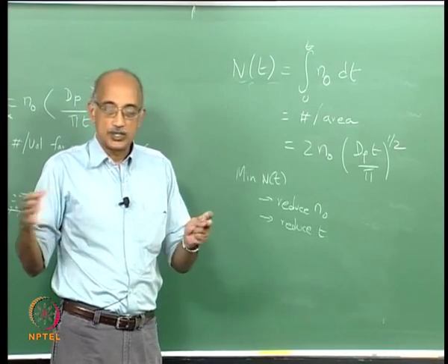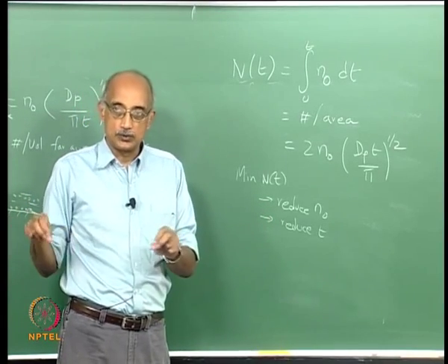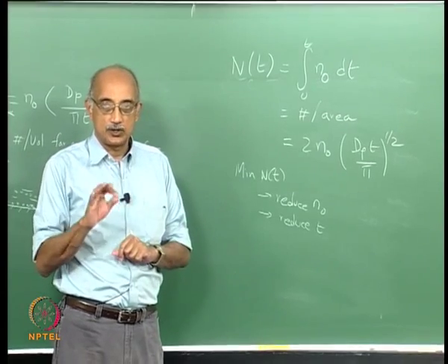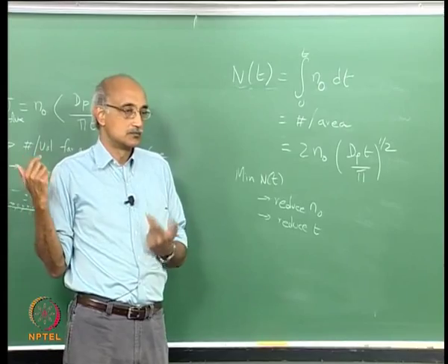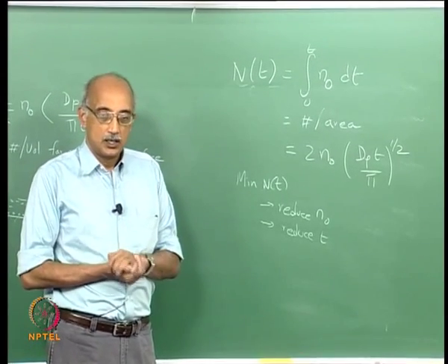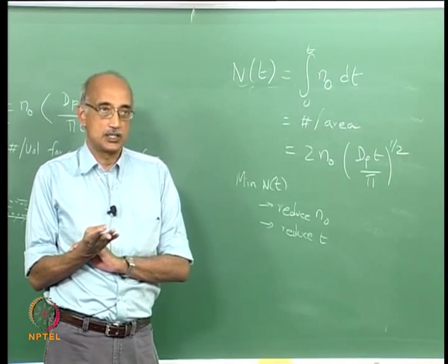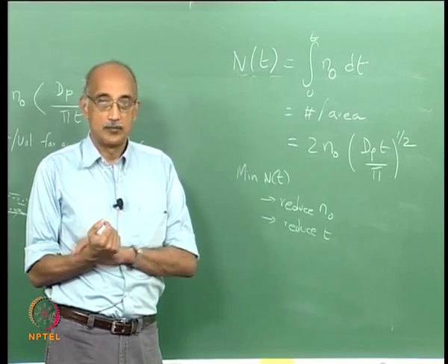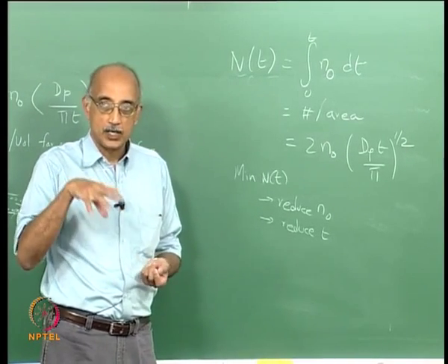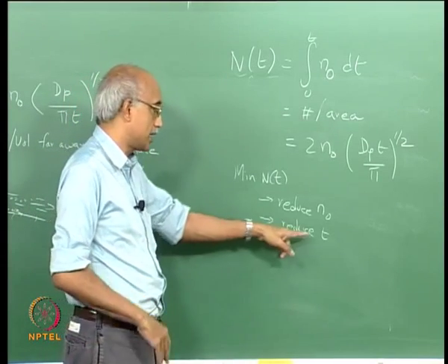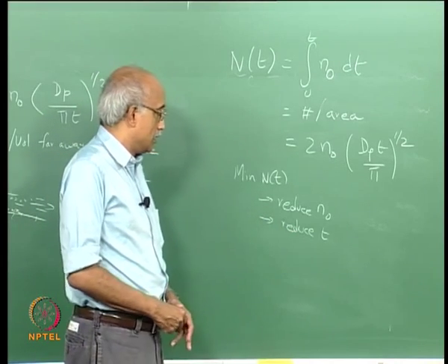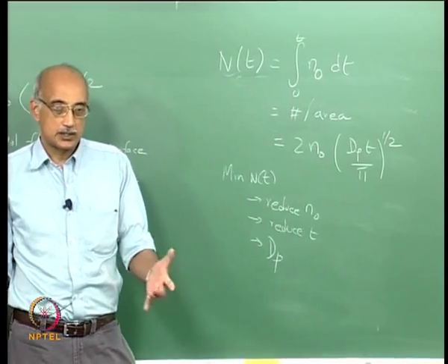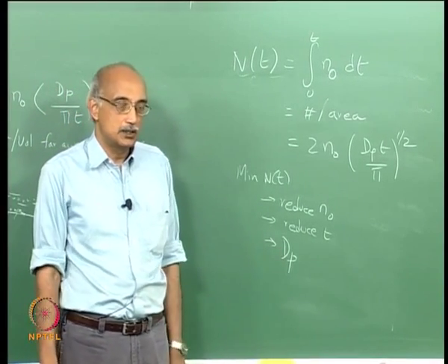So you don't have components just sitting around in a room for a long period of time waiting for somebody to use them to build a product. It's also known as just-in-time manufacturing. The components are delivered to the process just in time, just when you are ready to use them. So this combination of CFM, just-in-time, WIP minimization, all these strategies are good from a manufacturability viewpoint. If you talk to a manufacturing engineer, the first things that they'll preach to you is these aspects of efficient manufacturing. But it turns out that they also have very positive implications for minimizing the accumulation of contaminants on the surface, because they have a direct influence on time T. Of course, the other factor where you have some control is dP. So how do you minimize flux using dP as a controllable parameter? Well, you reduce dP, you reduce diffusional flux.